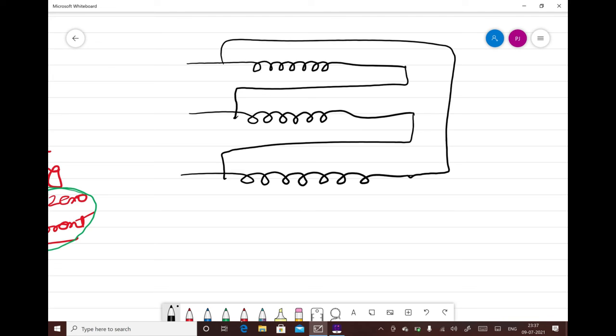This is your delta winding, and now we want to study how this delta winding traps zero sequence current. In case of any unbalance in the system or any unsymmetrical fault, suppose there are three sequence currents available to you: I positive, I negative, and I zero. Now when this current reaches this point, we are focusing only on the zero sequence current.